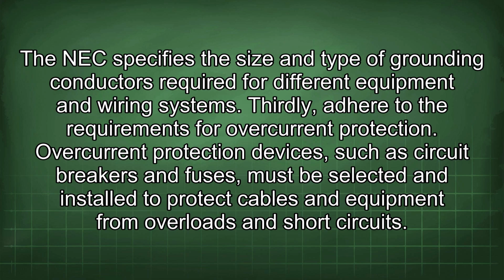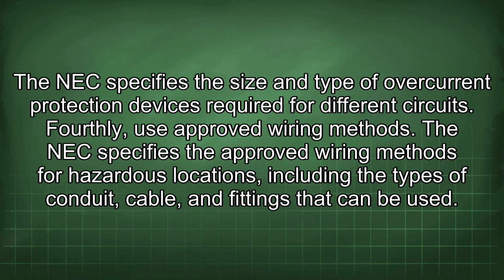Thirdly, adhere to the requirements for overcurrent protection. Overcurrent protection devices, such as circuit breakers and fuses, must be selected and installed to protect cables and equipment from overloads and short circuits. The NEC specifies the size and type of overcurrent protection devices required for different circuits.